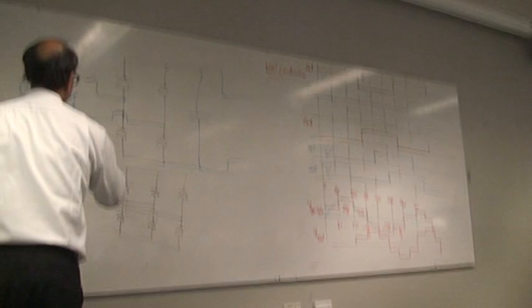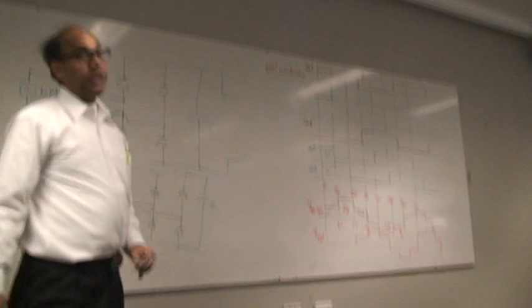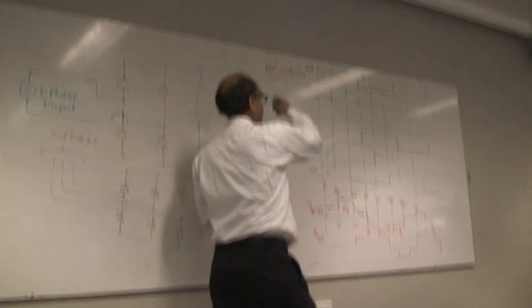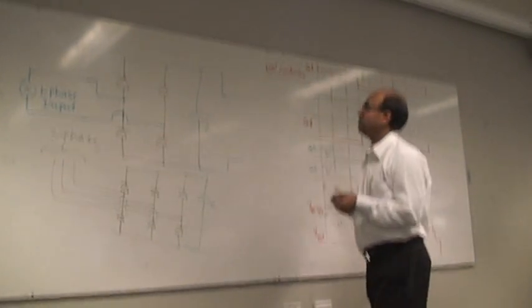So this is your 3-phase. Of course, you need to have the capacitor. This capacitor holds the rectified voltage, but this does not give you any change of voltage. So if you want to change the voltage and control that voltage, you have to have a PWM DC to DC converter kind of thing here.